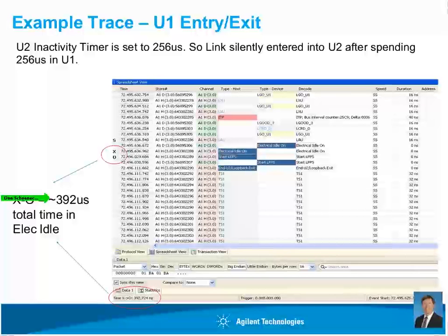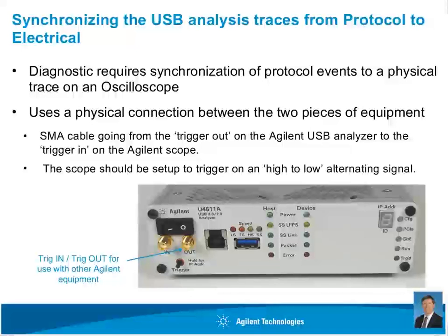Going back to tracing through your device development and making sure that it's operating, getting that signal out is an important part of the testing process too. And that's why the synchronizing between different devices is so critical. So whether you're synchronizing from a trace program in your software, or you're tracing to an oscilloscope, being able to get a trigger out to signal, okay, this is the event I'm looking for in this operation.